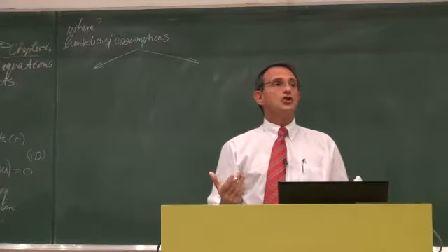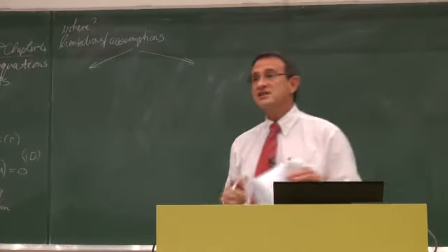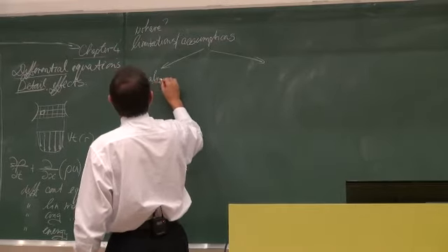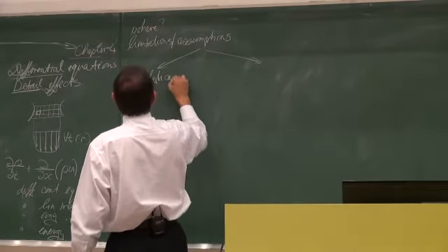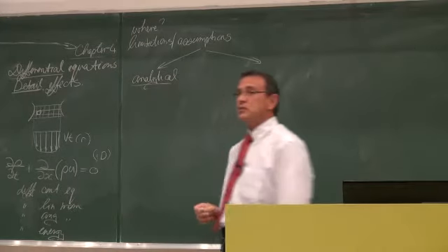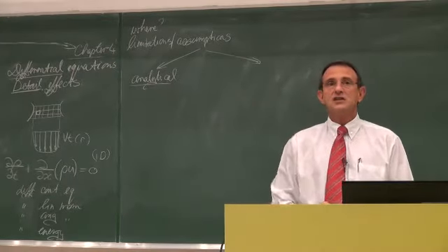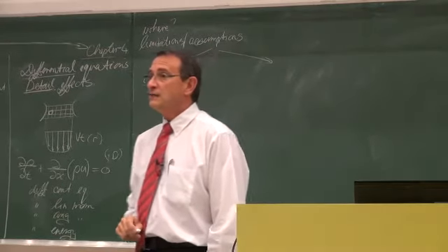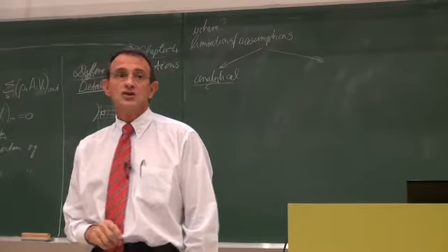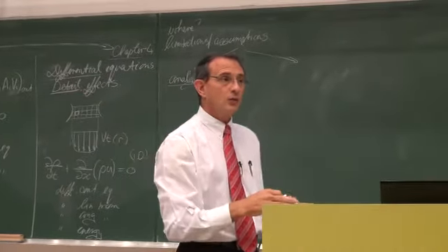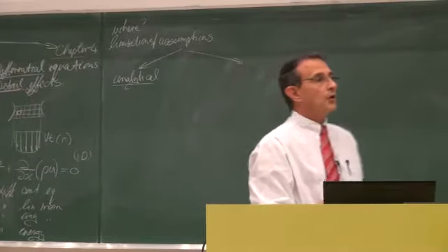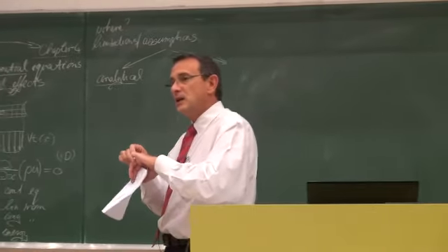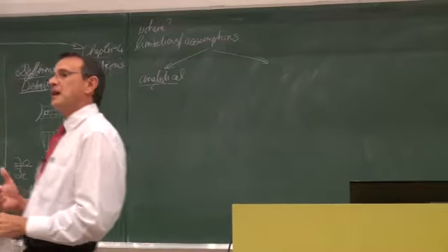And there are two things that you can use it for. The one is, we are going to derive a few analytical equations. So it is possible to take these differential equations and, in some cases, if you make lots of assumptions, and if the geometry is simple, like for example the flow through a channel, or flow through a pipe, or flow between two concentric cylinders, those cases can be solved analytically.